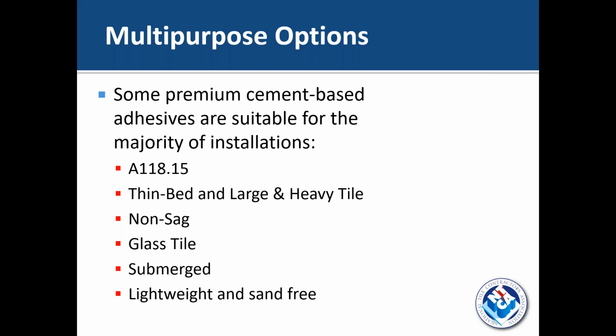So there are large and heavy tile mortars that meet A118.15. Again, that's the highest ANSI standard that can be used for both thin bed and large and heavy tile, that have non-sag characteristics, that can be used with glass tile and submerged, and even are lightweight and sand free. So that is an option as well. There are multi-purpose, almost all-in-one products.